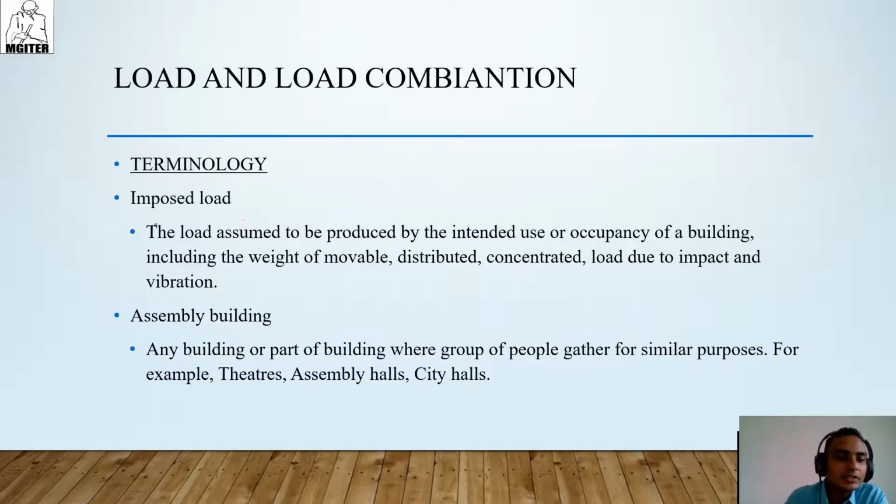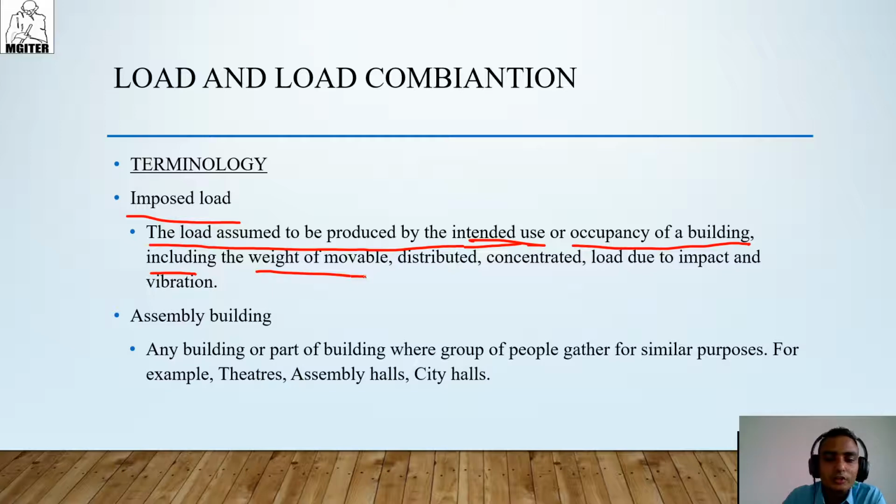First of all, you have to understand some terminology. Imposed load: the load assumed to be produced by the intended use or occupancy of a building, including weight of movable, distributed, concentrated load, load due to impact and vibration. Okay. Means imposed load will change by the occupancy and use of the building.